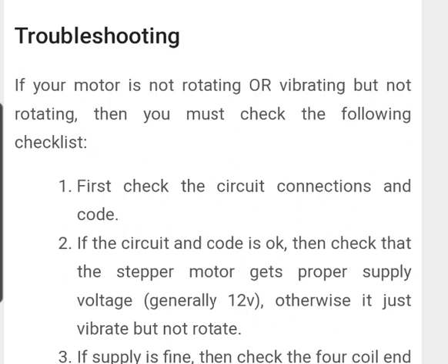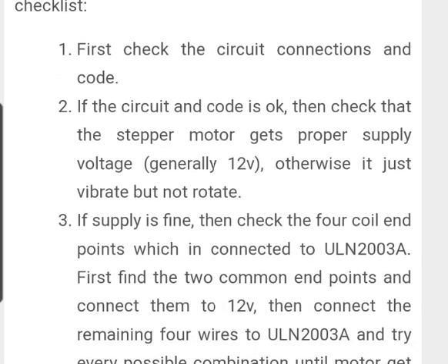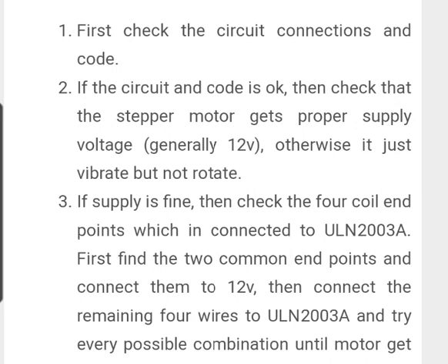Now, if the motor is vibrating but not rotating, then we have to check the following things. The first is to check the circuit connection and code. If the circuit and code are okay, then we have to check whether the stepper motor gets a proper supply, that is a 12 volt supply, otherwise it just vibrates but does not rotate.